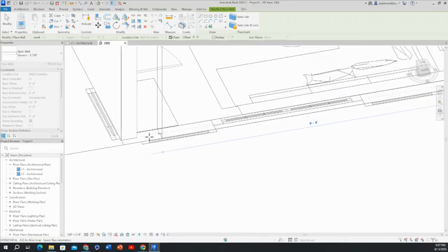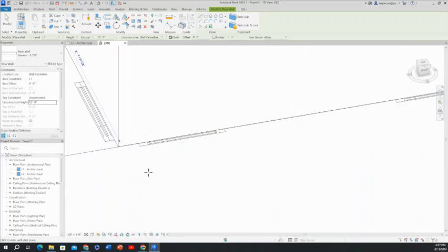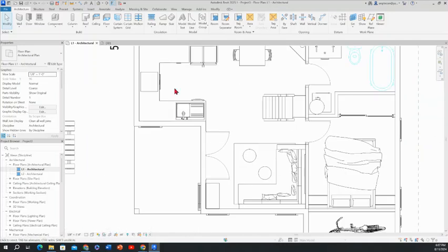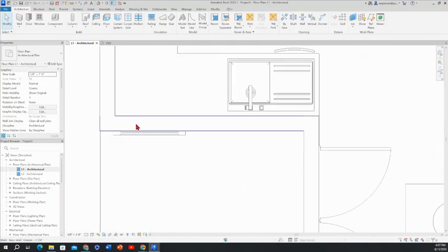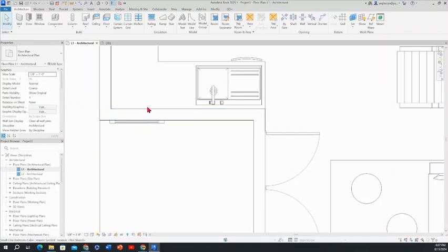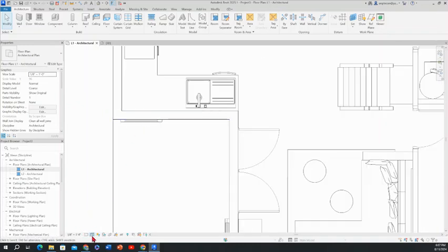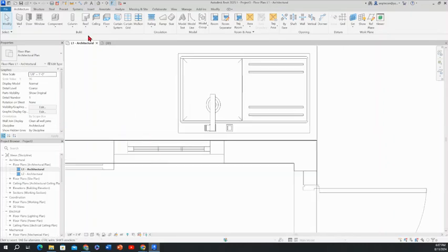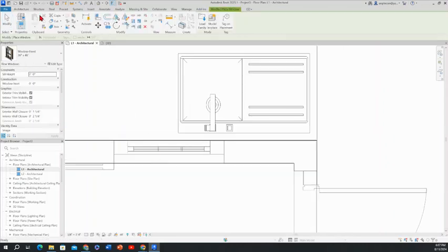Okay, and then here closing our walls, right, there we go. Now let's get back to our level 1, because you're gonna notice the way we did the walls. Now I don't see where the window is, so we're gonna have to go to our visual styles and switch it to wireframe so we can see through, and we can get the proper location of the window, and we can start getting our windows right on or in the proper location, right?